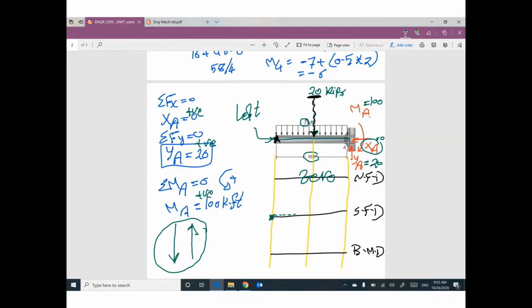Keep walking until you hit the equivalent value 20. Going down, so I will go down 20. Dotted, dashed. You're still walking inside the distributed load. Keep walking to the end of the distributed load. You have 20 here. What do you have at the end? We have a reaction YA, how much? 20. Going up, so I will go up to 0.